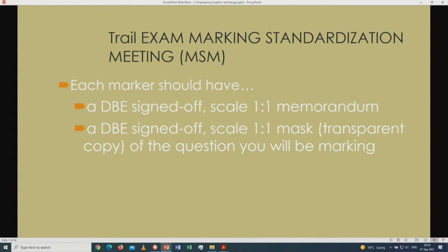And then the next thing I want to point out to you is that sometimes when you do make photocopies, it reduces the scale. So therefore, before you make the photocopy on a transparency, you first have to go on a normal white piece of paper, and if they say that this distance or this height is 75 millimeters, you have to check it before you go to the transparency and make a transparent copy of that. So therefore, make sure that the scale is 100%, a scale of 1:1, or even better, just take a familiar dimension and measure it before you go over towards the memorandum itself.